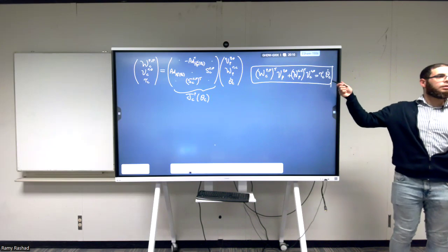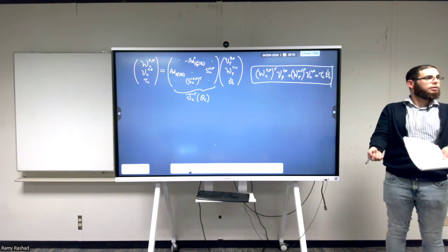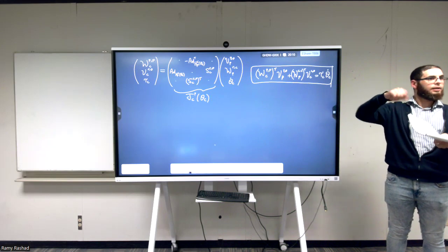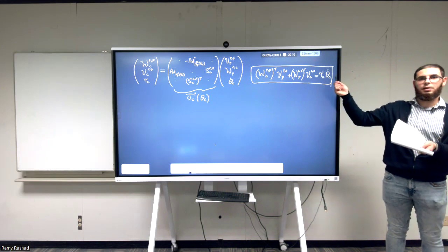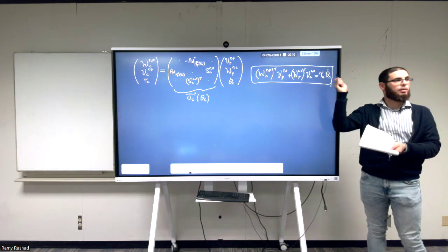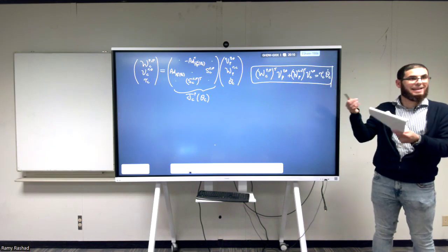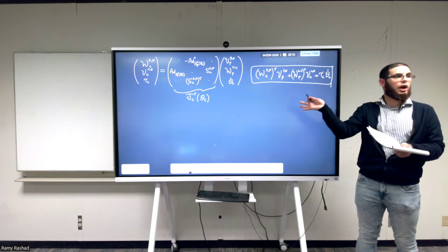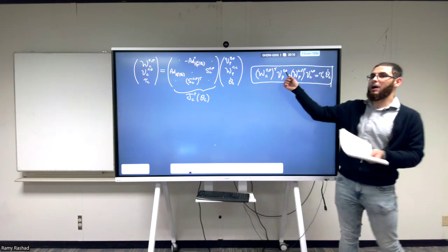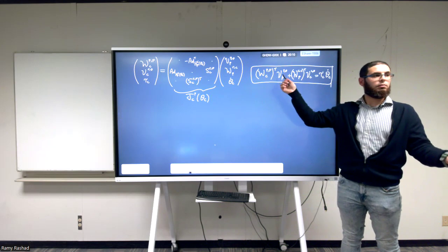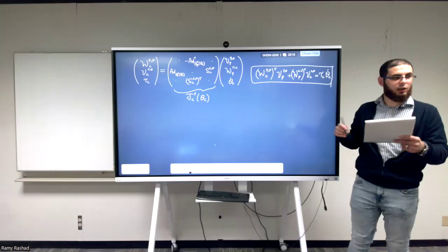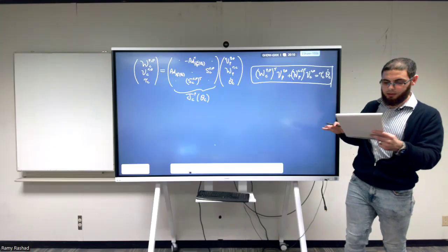This is the power that you supply by the actuator, right? Because you apply a torque by a motor, and the link starts to rotate by some theta dot. So this is the power applied by the motor, by the actuator. This is the power that goes to the child, and this is the power that goes to the parent.